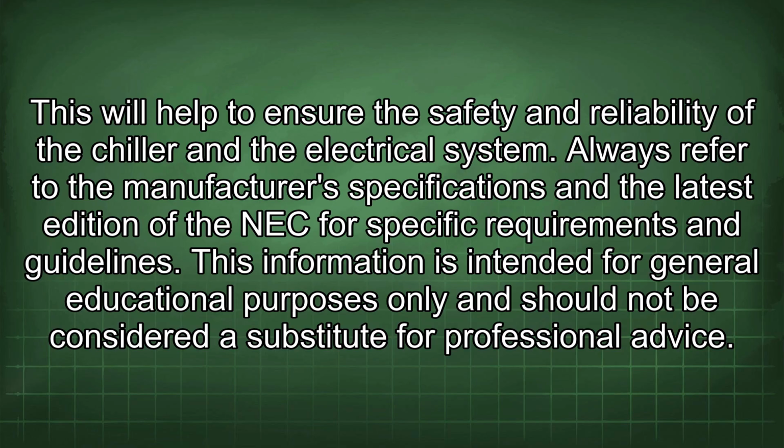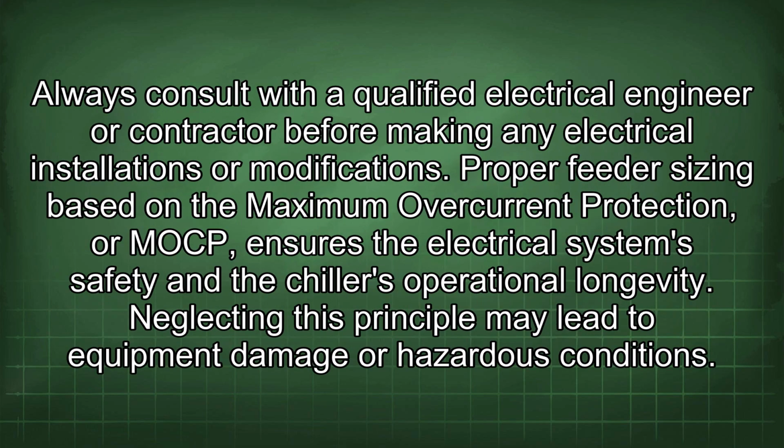Always refer to the manufacturer's specifications and the latest edition of the NEC for specific requirements and guidelines. This information is intended for general educational purposes only and should not be considered a substitute for professional advice. Always consult with a qualified electrical engineer or contractor before making any electrical installations or modifications. Proper feeder sizing based on the maximum overcurrent protection, or MOCP, ensures the electrical system's safety and the chiller's operational longevity. Neglecting this principle may lead to equipment damage or hazardous conditions.